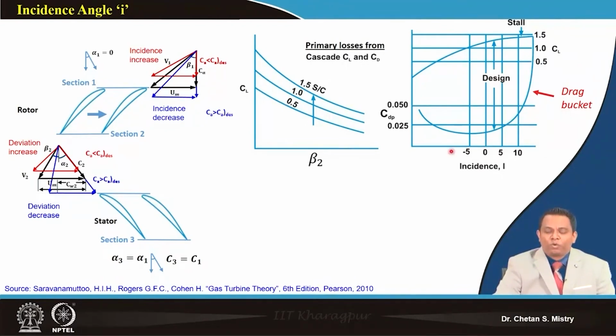Okay, now let's look at the other side when we are having a negative incidence angle. You can see my lift is still being generated, but it's lower compared to what lift we are expecting. So the meaning is this is what is giving us the idea that my pressure rising capacity of the particular aerofoil is decreasing. Okay, so this is what we need to remember, this is very important. And as I told, as aerodynamicists, many people used to say this as angle of attack, but in our conventional language we are writing that as incidence angle.